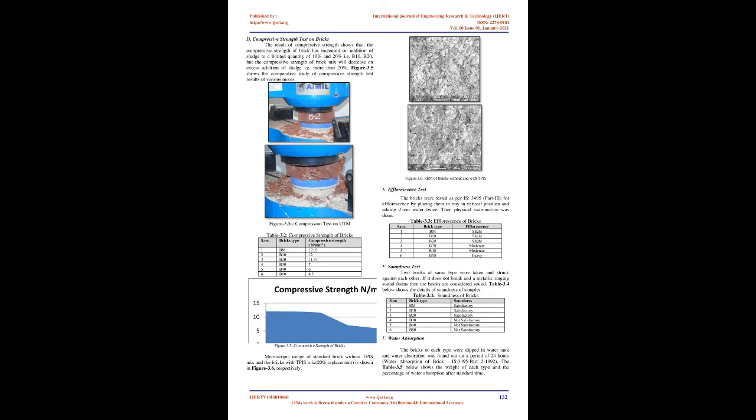Compared to the tested common commercial brick, the thermal conductivity has reduced with increase in TPIS. The optimum low thermal conductivity proposed was 0.700 W/mK, which has 30% TPIS as partial clay replacement. The normal thermal conductivity of brick is in the range of 0.7 to 0.9 W/mK.